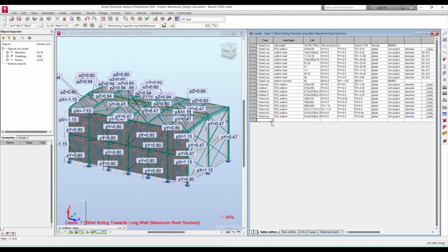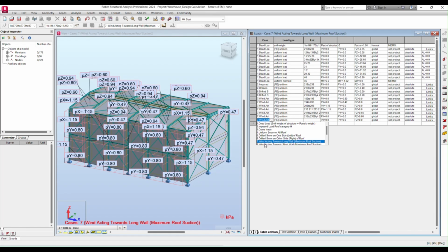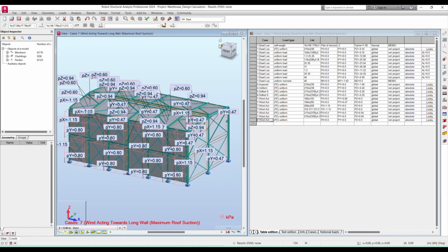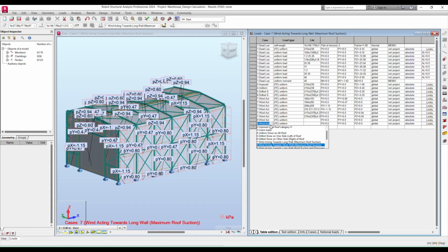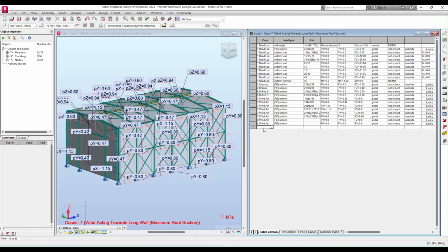Similarly, with the same method, we are going to apply the wind load of the 8th case, which is in the x direction, the shorter direction. This is applicable for all the cases. So we need to create all 6 load lines for 8 also, because 4 sides of wall cladding and 2 sides of the roof cladding we need to create.